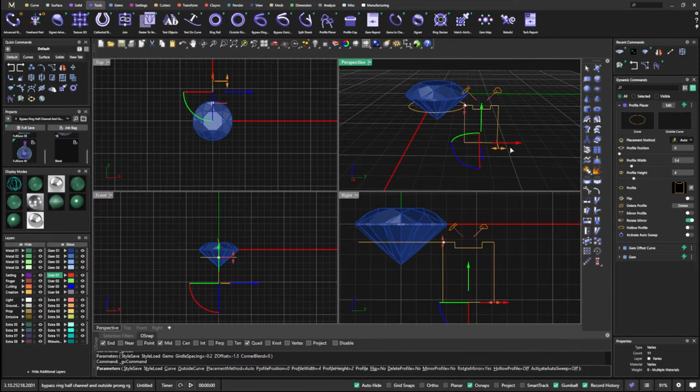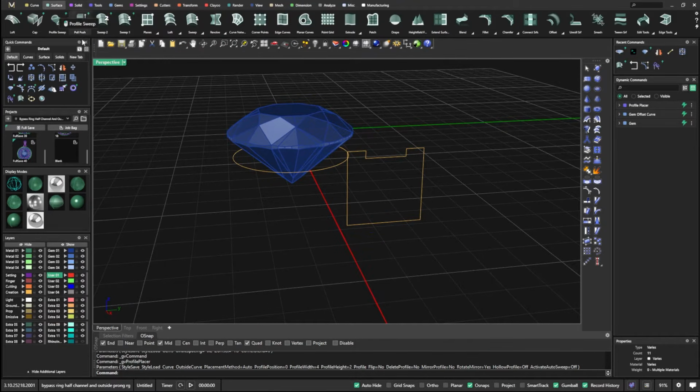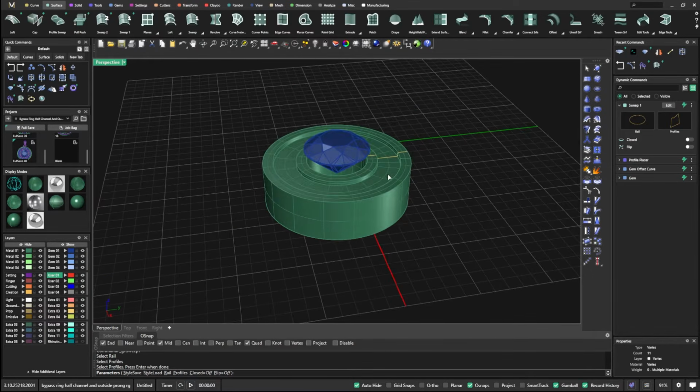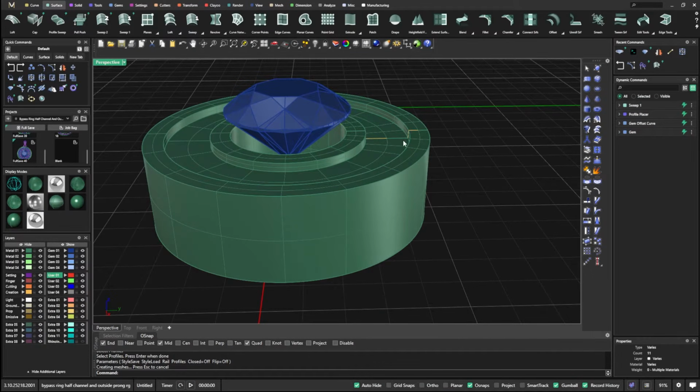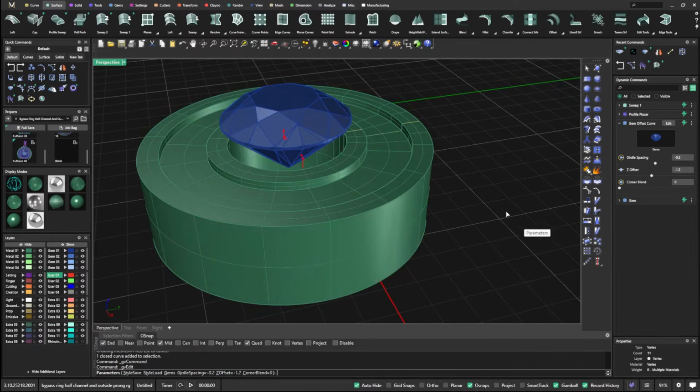So that's another way, and we still have total control on it. So we're making that channel larger, smaller, and our rails and everything. Let's see. So we'll do something like this, and we'll bump it over so it's right there at our edge, right? And we'll accept it. Okay, now we'll go to that surface, go to surface 1, go from here to here to here, and we have all that layout, and we'll accept it, right? And now we have this curve here that we can manipulate, right?